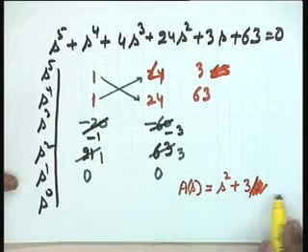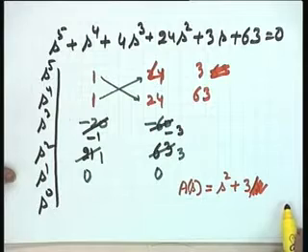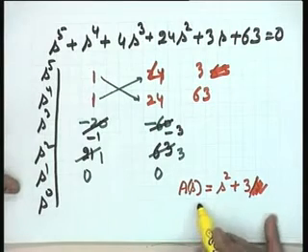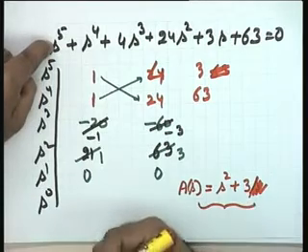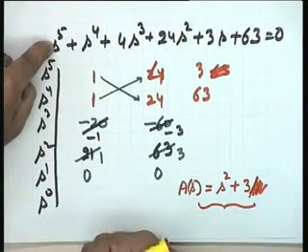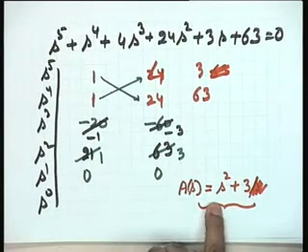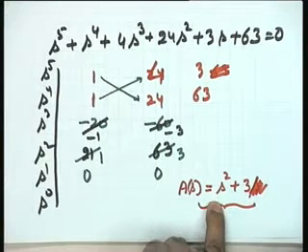Okay? So, this becomes the auxiliary polynomial of the system, and the result is that the auxiliary polynomial is definitely a factor of your original characteristic equation. Since the auxiliary polynomial has roots at what location, please? On the imaginary axis.